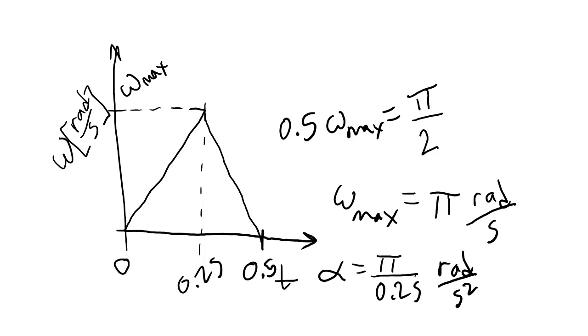For our application, we need the motor to be able to exert the 140 ounce inches of torque at all of these speeds, including omega max. We need to pick a motor for which the speed, omega max, and the torque, 140 ounce inches, falls below the torque speed curve for the motor.